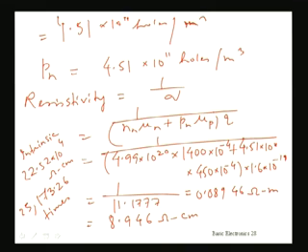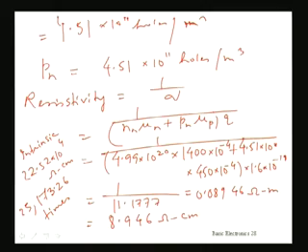So this effect of doping an intrinsic semiconductor by an n-type doping agent is very important, because it has brought down the resistivity, meaning it has increased or enhanced the conductivity so much. So this example illustrated the effect of doping an intrinsic semiconductor by an external n-type impurity atom that we have learned today.